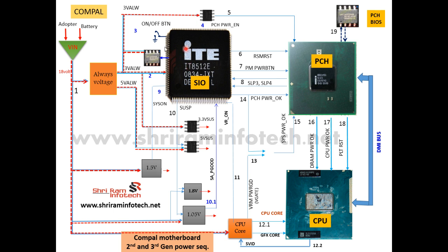So now the next is my power button. My third step is the power button, which is called the EC power button, power on, or NBSWON, something like that. There are maybe 2-3 names given for the power switch: NBSWON, power on, or on off switch. Okay, so here you can find 3 volt, and the other leg is connected to the ground.